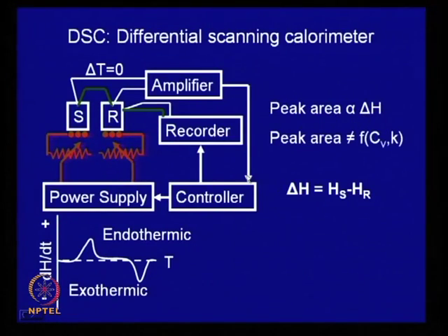And some of these instruments are sometimes also coupled with a load cell, so you can also monitor the change in weight as well. But let us not bother about it. I spent some time on thermal analysis because very often, to explain how the microstructure evolves in a material, we will be looking at the cooling curves and how the transformation takes place. You can get a lot of information from DTA and DSC plots.